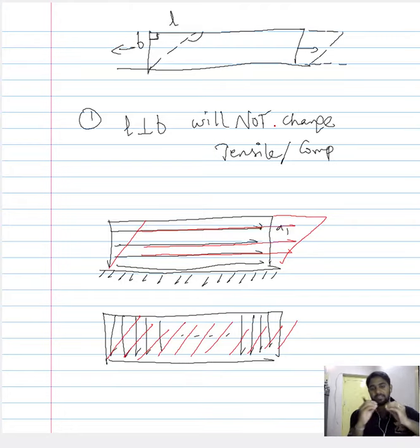The other is that the size of the horizontal element, which changes during compression or tensile loading, will not change during shear deformation. The vertical elements remain parallel in nature, and the distance between them, which changes during tensile and compressive loading, will not change during the shear deformation, but rather they get tilted.